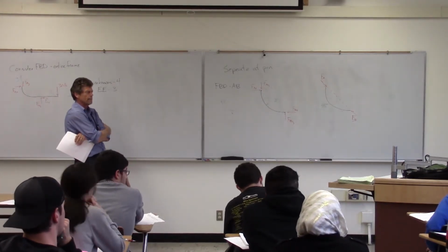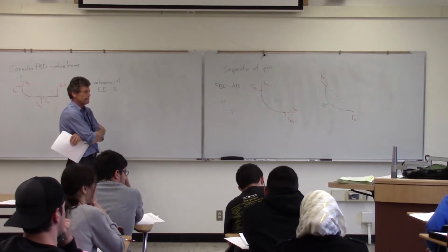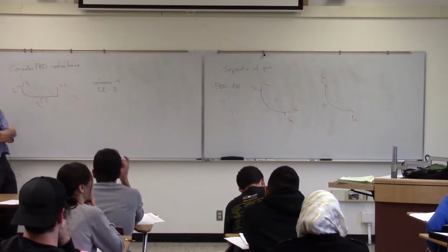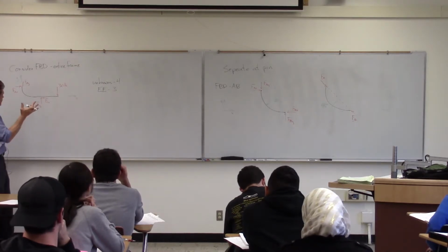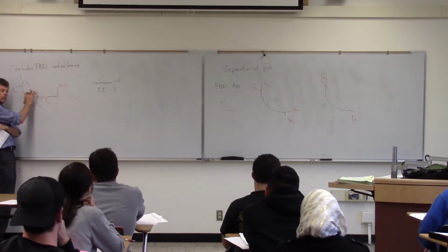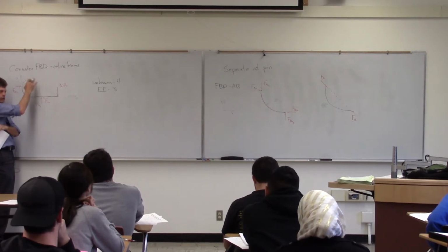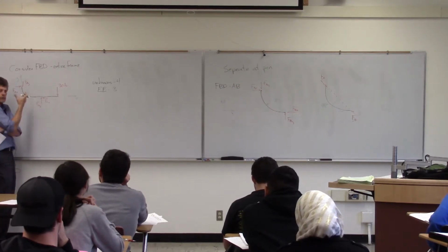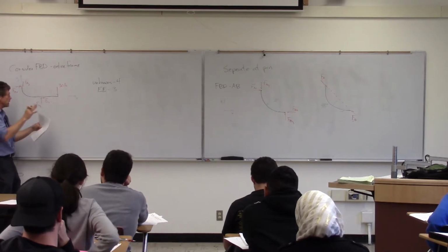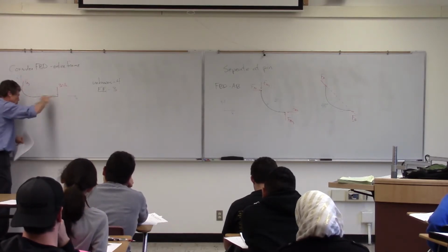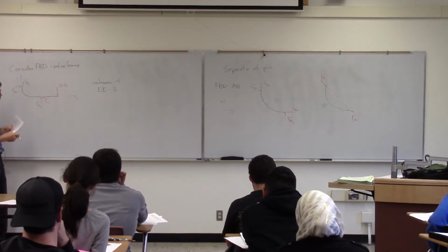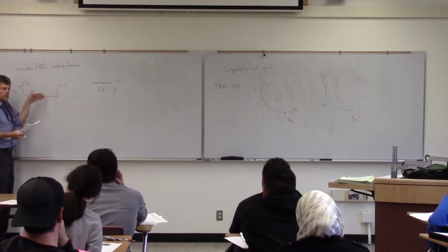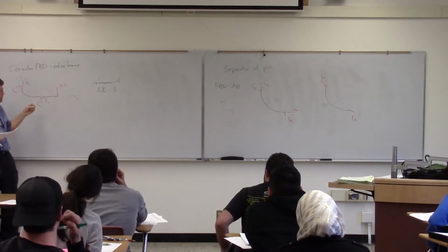Is that because you just consider this all one rigid body, so no action is really happening at that pin? Exactly. So it meets all the criteria in terms of a rigid body, that it's not deforming there, it's not bouncing up and down and stuff like that. You'll get into dynamics and stuff like that. So it's basically in position, it's being held there, it says it's in equilibrium, so it's static, it's sitting there in a stationary sense there. So yes, it's working, but basically we don't see it because it's internal to that free body diagram that I've drawn there.